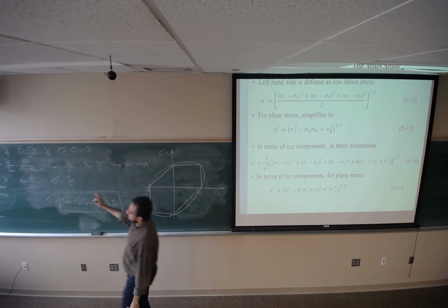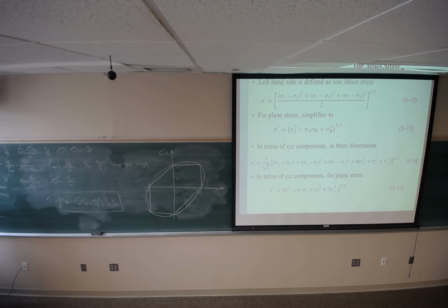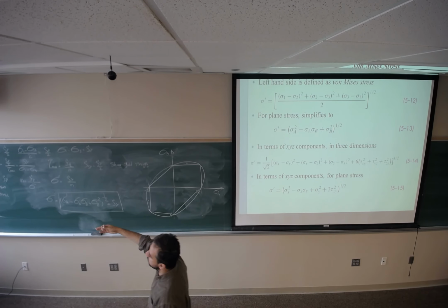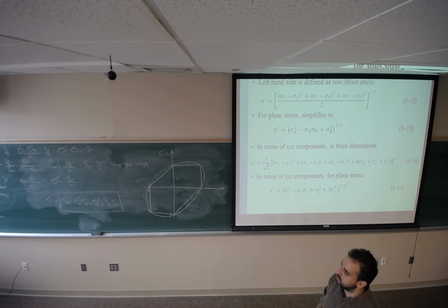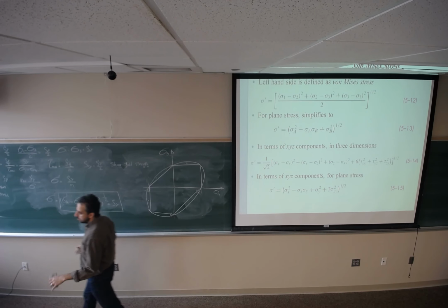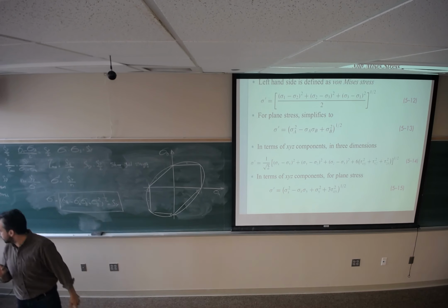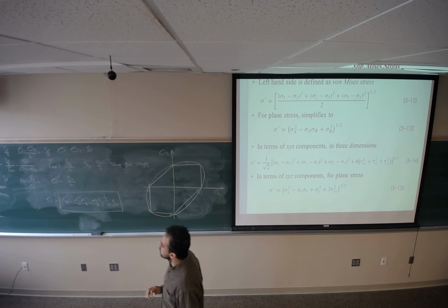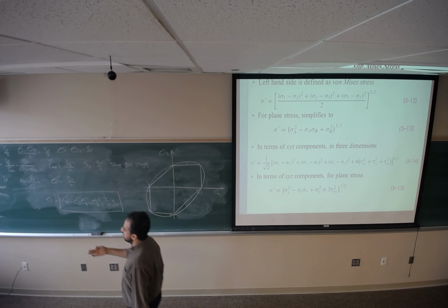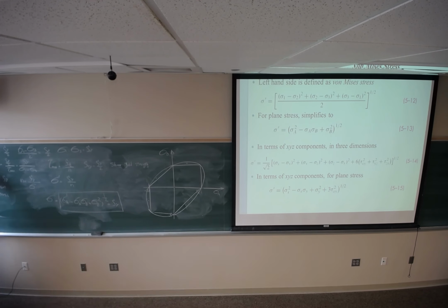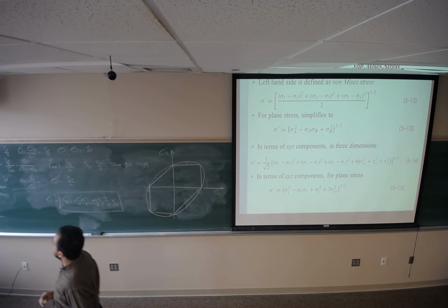For doing the analysis, if you are not asked which method should be used, you should use the distortion energy theory. What do I mean by analysis? If you are given a mechanical component and you want to see if the failure occurs, you are going to use this to check that. You are not going to do design. You are just going to check, doing the analysis. But if you want to do design and you were not asked which one should be used, it's better that we be more reliable and use maximum shear stress theory.